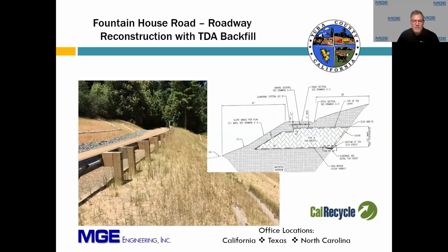All right, thanks, Martin. One thing I want to reiterate here is the native soils were not suitable to be reused as engineered fill. So if we didn't use TDA, we would have had to import. Instead of paying to have imported borrow, we were given TDA delivered to the site near the projects for free. So it was really a win-win for Yuba County, our client. Here's the picture of the repaired condition. This was the same road you just saw in the last slide.